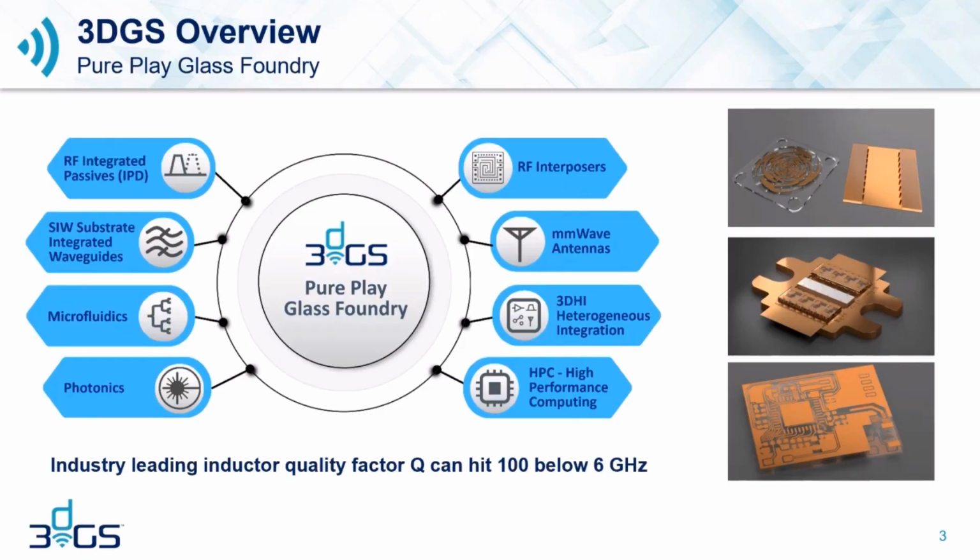And that is important because you can wet etch that ceramic. So it doesn't matter if you have 2 vias or 22,000 vias in your substrate, they all get cleared out at the same time. So it's quick and cost effective. The etch profile of this wet etch is also very anisotropic, so we're able to hit 89-degree sidewall angles and 8:1 aspect ratios. That's really important. We're able to create dense routing and compact low-loss RF structures.